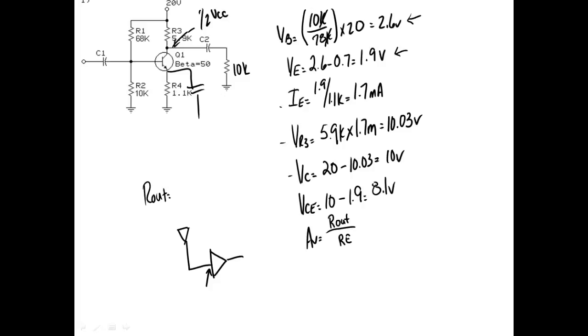So my first amplifier is supposed to have extremely high what? Input impedance. Extremely high. What we do is sacrifice gain for a higher input impedance. If you don't bypass RE, then RE is seen as RE times beta. So if you've got a beta of 100, then the input sees over 100K of resistance. But if I don't bypass this, we sacrifice what? Gain. So we sacrifice gain for high input impedance, but we don't get much gain.